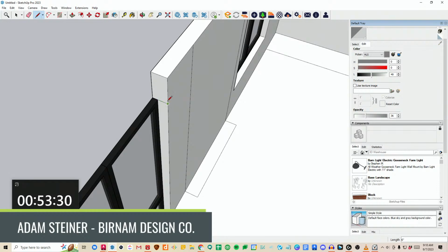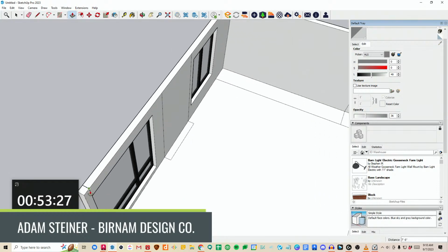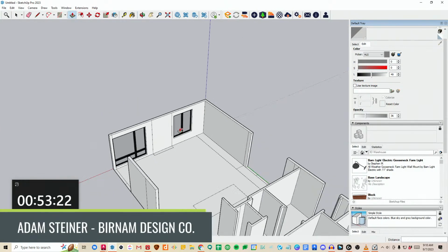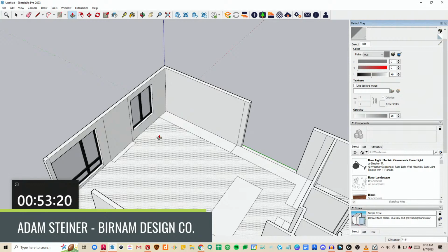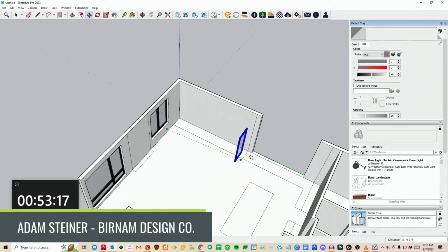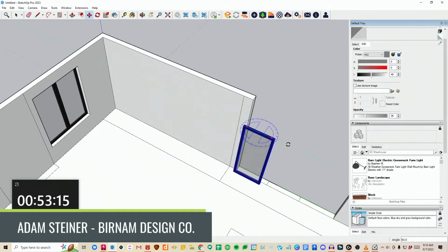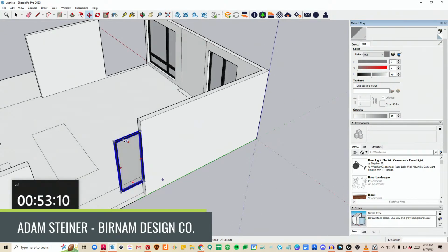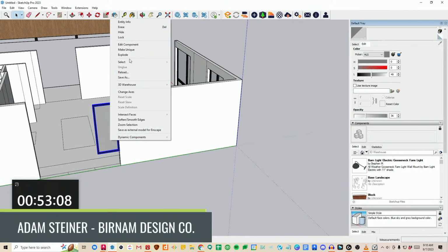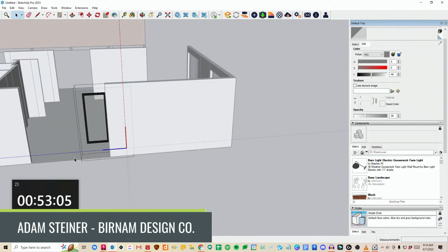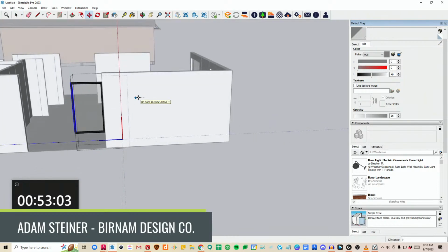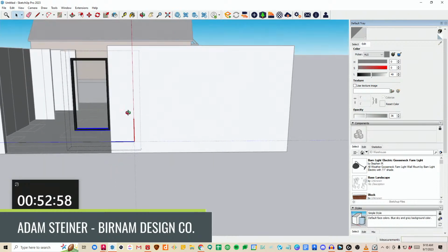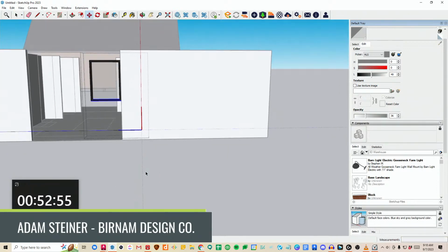All right, then I'm going to bring this line across here to draw the header on the inside of the room. Okay, we're getting somewhere. All right, let's do that triple window on the back of the kitchen. Bring it down a foot. And so I need to make this window unique as well, because those are wider and shorter. So I think it was 12 inches. No, it was only 6 inches wider. Yep. So those are 30/40 windows. I'll bring it up 2 feet.